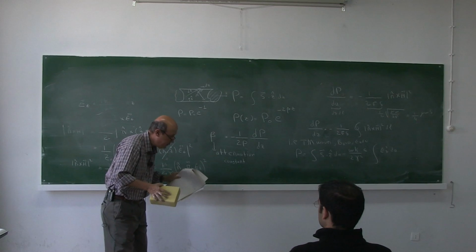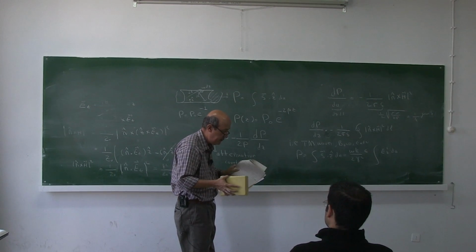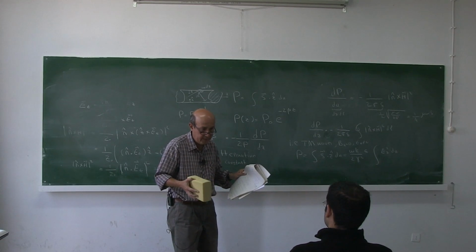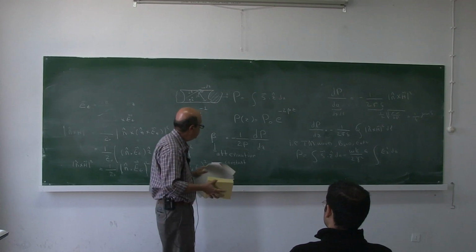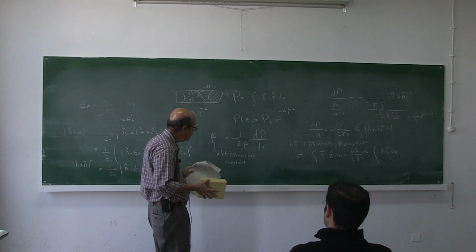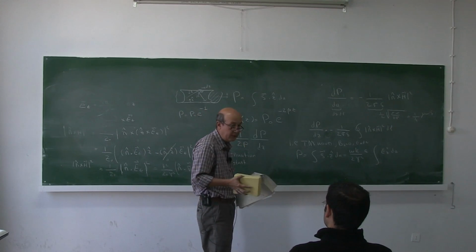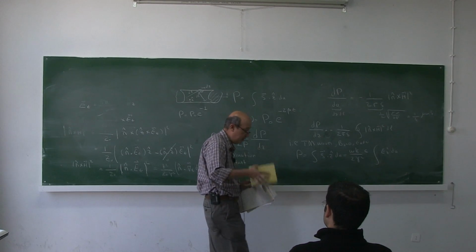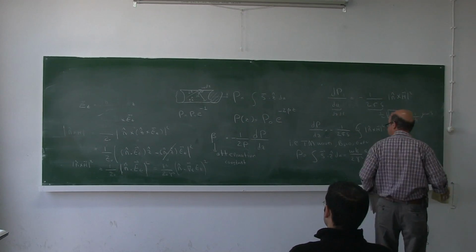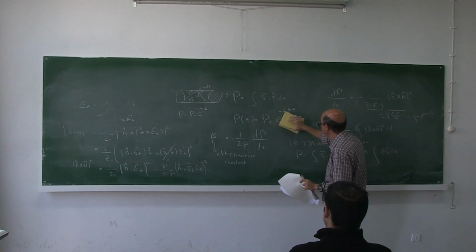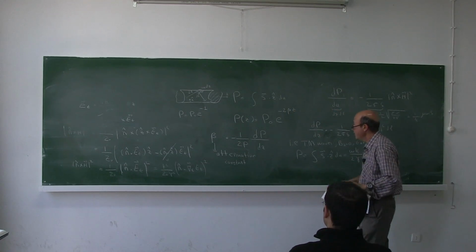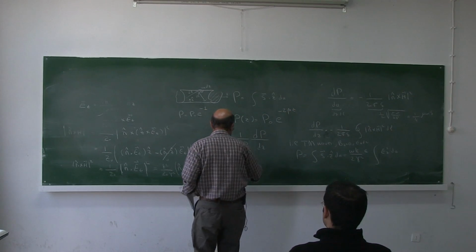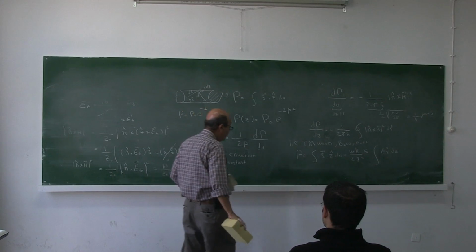First, our waves in the propagation direction are plane waves. Since the walls are not perfect, our wave number has an imaginary part. And our transmitted power goes with E squared or B squared. Therefore, our transmitted power decreases by the square of the amplitude of the field. And that brings us e to the minus 2 beta z. If the transmitted power is in that form, you can solve this equation very easily and you can find the attenuation coefficient.